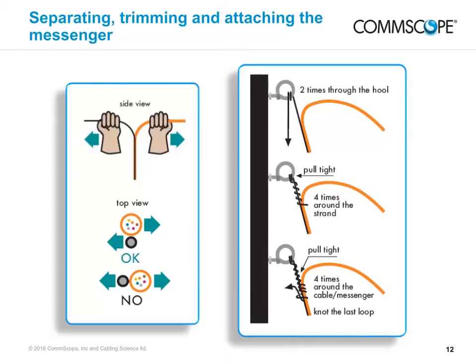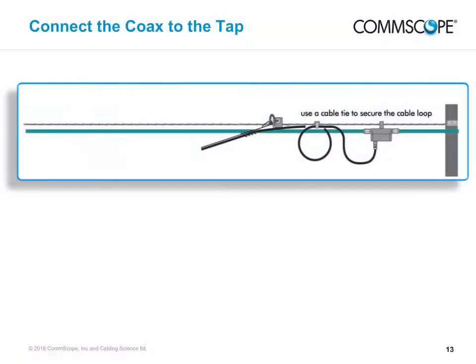Attach the cable to the building. Using the scissors pull, strip the unused messenger from the cable. Secure the cable to the building with cable clips or similar devices. If possible, place the cable along architectural elements that will hide it. For coaxial cable installations, the cable should be connectorized per the instructions on coax connectorization. Some systems like to protect the connection with a shield, a physical covering to protect against tampering. Place that over the connector now. You will require an F-connector tool to tighten the connection.